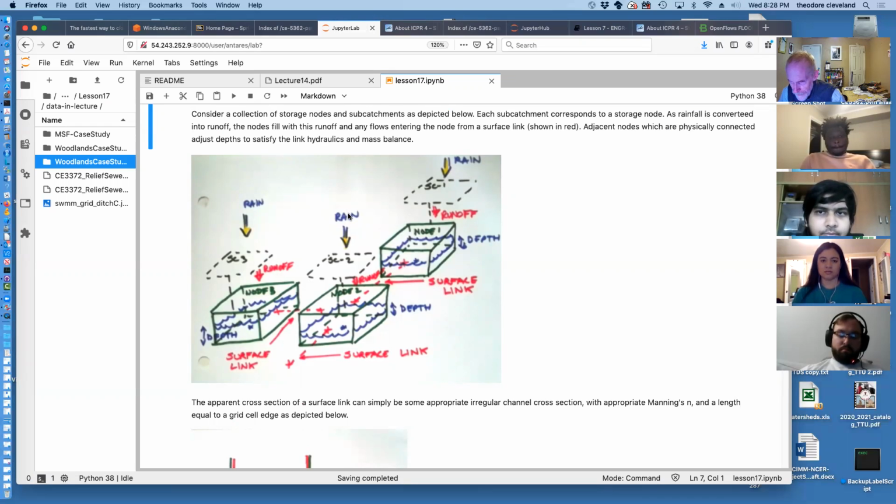So if perhaps 1 inch an hour of rainfall comes in, and one of these subcatchments is an acre, the expected runoff, if there's perfect conversion of that rainfall into runoff, would be a cubic feet per second that would eventually come off that drainage area. And that would scale directly proportional to the area and proportional to the fraction of rain that gets converted to runoff.